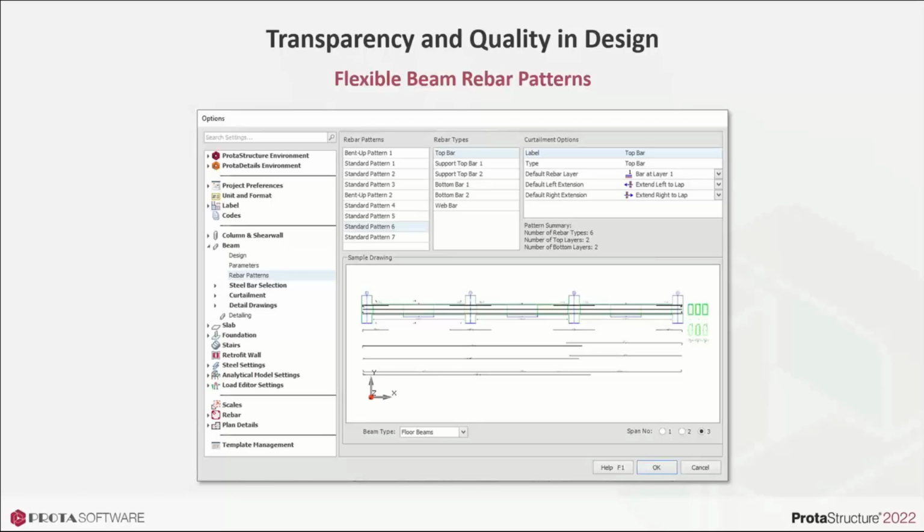In the beam settings, you now select among various patterns, and you fine-tune the properties of these patterns and the behavior of the rebars in a certain pattern, so that all the beams in your structure will be designed according to the pattern you customized.